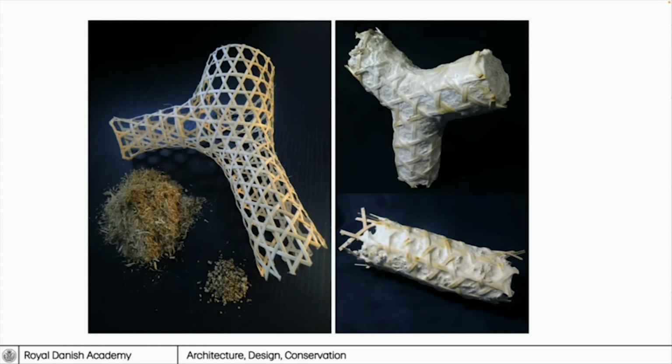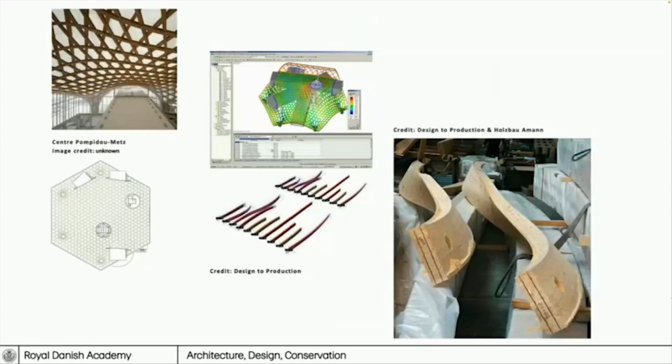a construction system where essentially we can think about producing mycelium elements as a form of casting technique. And rather than thinking about the casting element as being something that is throwaway, might we be able to make it as something that is a stay in place and can also act as a reinforcement? So you see some initial studies here where we're getting some very nice colonization. The stay in place mold and reinforcement really starts to become a bound part of the unit of the composite.